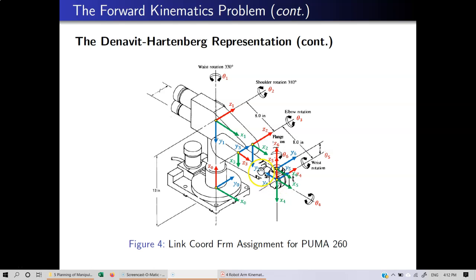So this is joint number 4, and this is the axis of rotation, therefore this is Z3. Alright, so if we extend Z2, we can see this is the intersection. So that is the origin of coordinate frame 3, and the cross product between Z2 and Z3 can be this direction or upwards. So we choose downwards.